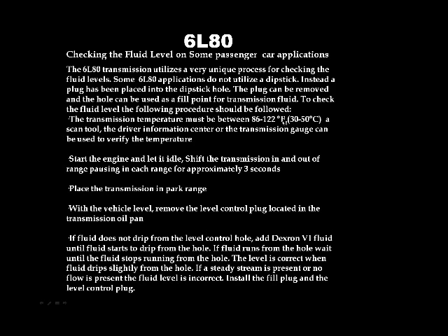Now the fluid temperature that we're talking about, as you can see in the middle of the screen right here, is 86 to 122 degrees Fahrenheit. You can look at that fluid temperature via several different approaches. You could use your scan tool. You could use onboard diagnostics, because most of them have a driver information center that will give you that information. Or you can simply roll underneath the transmission with a temp gun and shoot the pan. But the bottom line is, very similar to the Chrysler unit, you want to make sure you have the correct temperature prior to trying to figure out what the oil level in the transmission is. If you do not, you're going to end up either overfilling or underfilling this unit, which is obviously going to be a detriment to the operation of the transmission.